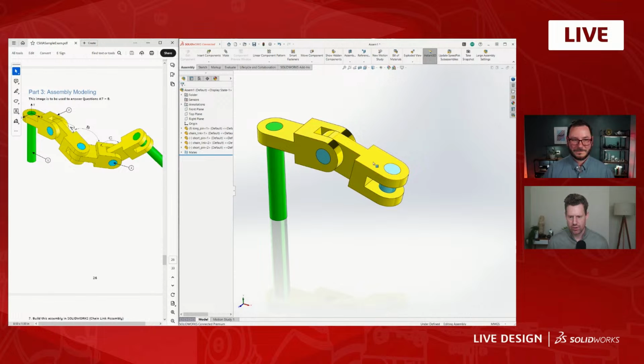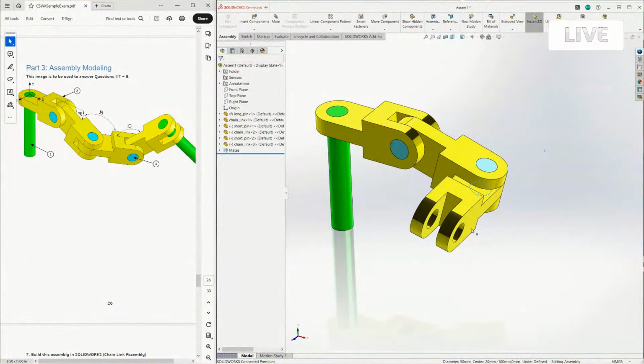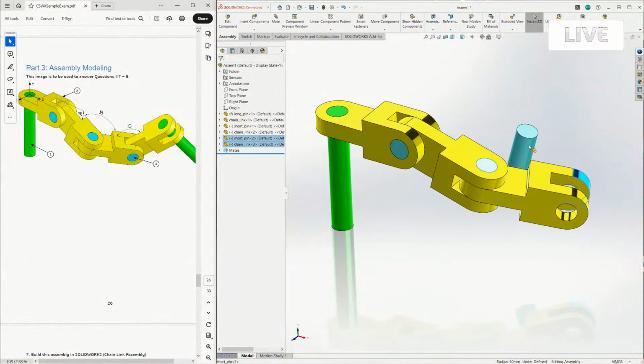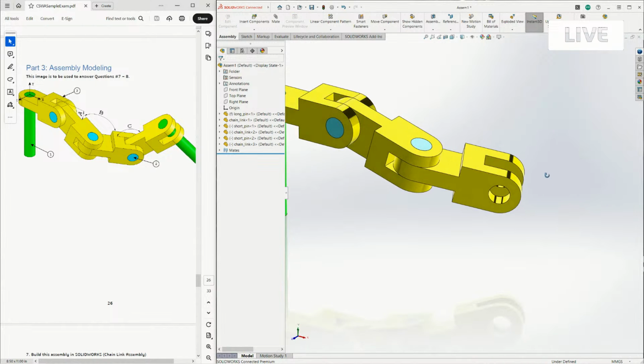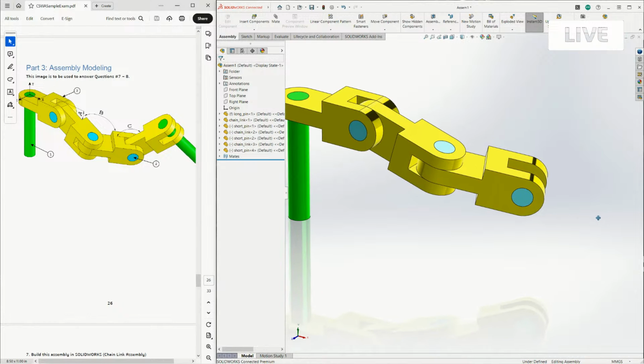I love that. Very quick. So I still have some rotation there, so I probably want to create an angle mate here, but I'm going to do all those angle mates at the end. So I just really want to repeat this process a bunch of times. I can hold Alt, drag to this edge, let go of Alt, hit Tab, and I can drop that in there. Control drag this one. There we go. Control drag that. Hold Alt, drop it on there, let go of Alt, hit Tab, and it drops in place.